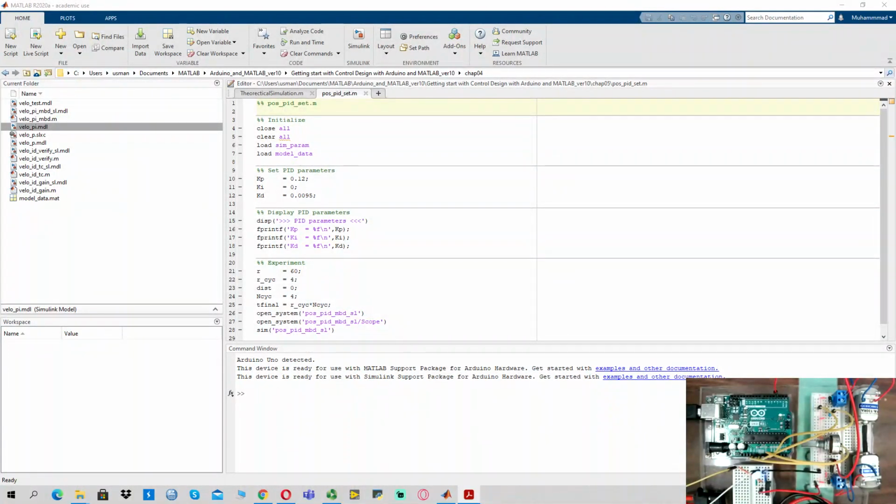You can observe that when you have proportional control in real time, you can remove the steady state error by just kicking in the integral control, and see a clear change in the transient performance of your system, in this case the motor speed control system. In the last part we will also give an overview of PI gain design with the pole assignment method, where we'll place the poles at different locations to make the system response better. These are the four topics that we'll cover in this demonstration of the motor speed control experiment.